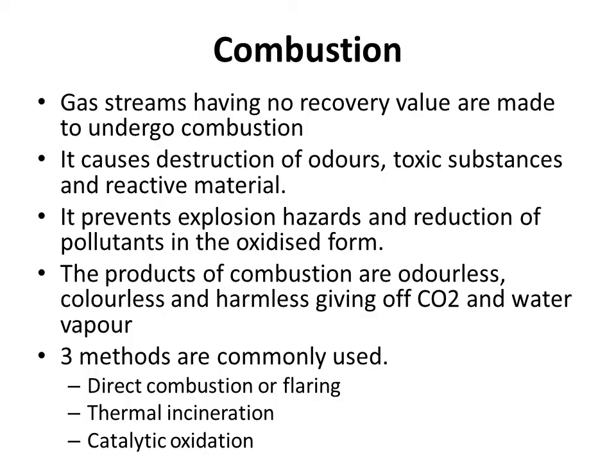Combustion. Many industrial processes which produce gas streams have no recovery value. So, absorption or adsorption methods may not be economically feasible. This method causes the destruction of odors, toxic substances, and reactive materials. It prevents explosion hazards and reduces pollutants in the oxidized form. The products of combustion are odorless, colorless, and harmless, giving off carbon dioxide and water vapor.